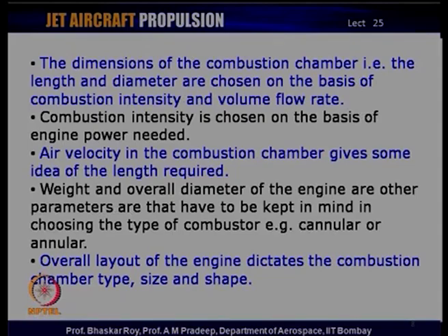And that tells us that the air velocity that is operative inside the combustion chamber does decide what the residence time is of the working medium air inside the combustion chamber to absorb the heat release and then carry it with it into the turbine. So, this ability of the absorption of the heat release into the working medium air inside the combustion chamber is something that has to be decided by the combustion designer.